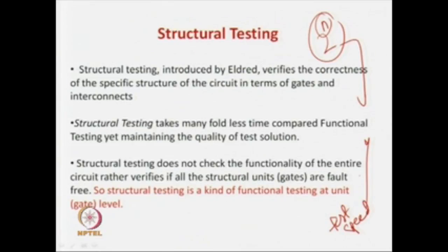But moving up test speed, fine, you can go up to megahertz, you can go up to gigahertz, but going to terahertz or even higher will require a tester which will be so expensive that you can never make up a profit by selling the chips. We can make a profit by selling the chips if the yield is low, that is, if 50% of the circuits are defective, so you can throw out 50% of the chips and sell the other correct 50% in the market and make a profit. That is absolutely fine.